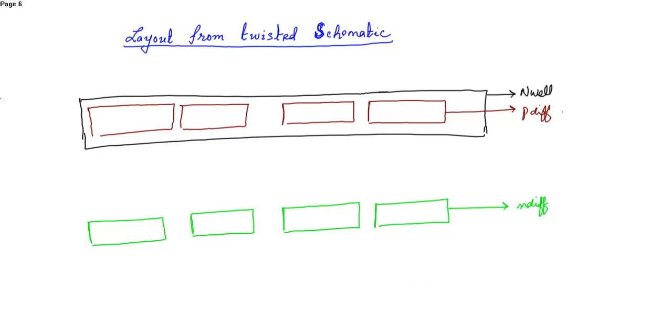And diffusion layer. So now these two are the inverters, these two are the transmission gate. So design the inverter first. I have to draw the gate of the inverter. This is also the gate of the inverter. Then this is input A and B. If you see the transmission gate, then the gates are oppositely connected.